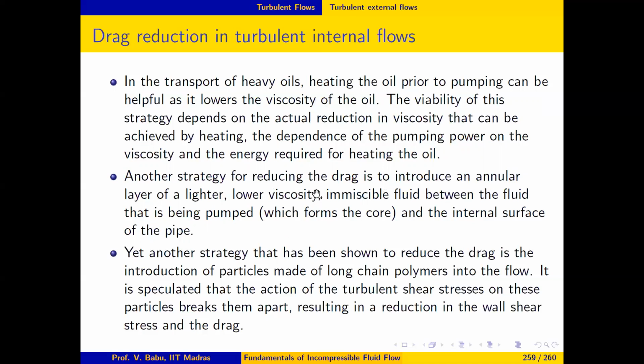The only difficulty with this strategy is that the interface between the annular layer of fluid and the core layer is highly susceptible to hydrodynamic instabilities, and very quickly the interface cannot be maintained in the manner in which it ought to be maintained. Some detergents and other additives can be added to suppress this instability, but that is a challenge that has to be overcome for this strategy to be viable.